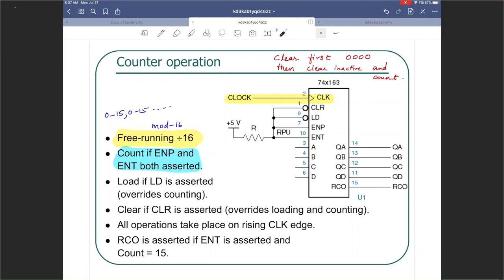You guys see that? Now this will play a crucial role in the studio today. Because we are simulating this counter, uncertain is not an option, right? Uncertain means X. You will never see the counter move. Even if you connect everything properly, and if you have set up everything about your simulation correctly, if you do not know how to get things started, then the counter will not count.